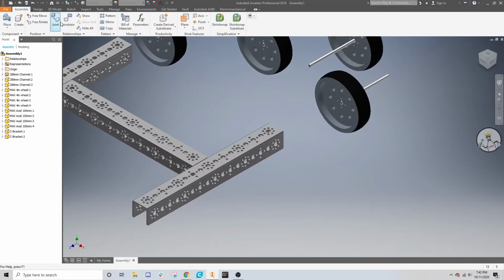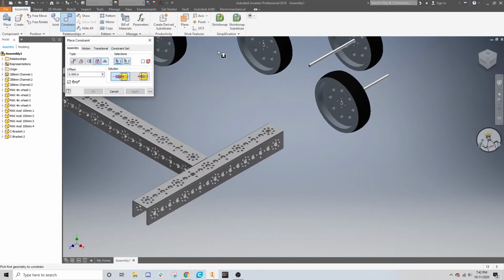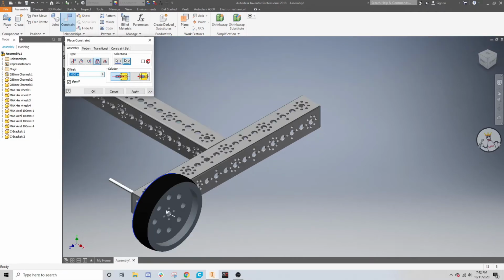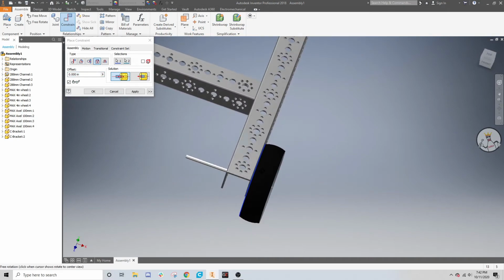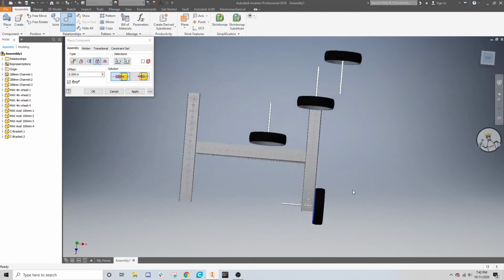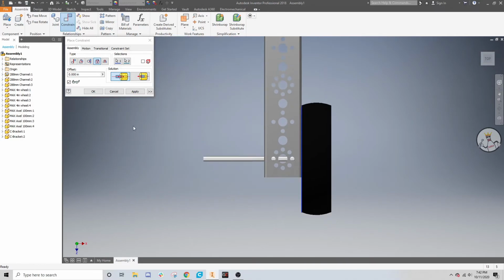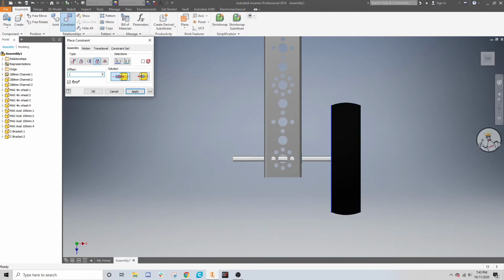And then for the wheels, it's kind of the same thing as putting the axle in the wheel. Just insert, do this, and then click on this hole. And this isn't going to work too well for a wheel, so we're going to add some space between it and this channel. So I'll go to this view so you can see it the easiest. And then, just so we can see the spacing, we'll say 1 inch. And as you can see, it moves that way.